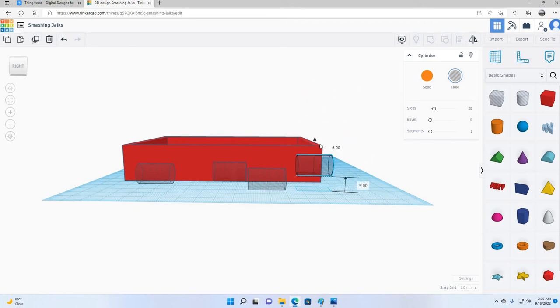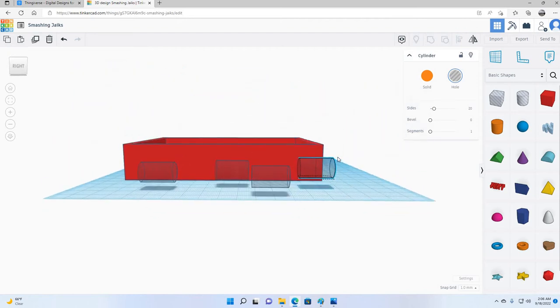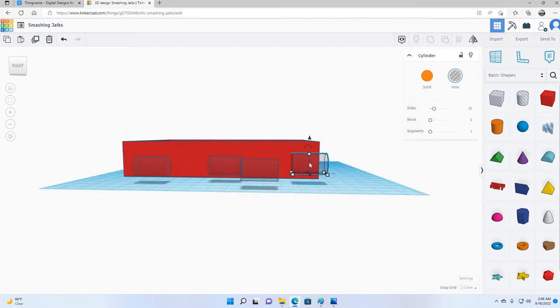In this case I do need it to be up a little bit because I know the thickness of my back wall, as it will be, is 4. So I actually want this hole to be pretty centered in the side walls. So I need to make sure it's at least more than 4. So 3 above 4 sounds good to me, so we're going to call it 7.